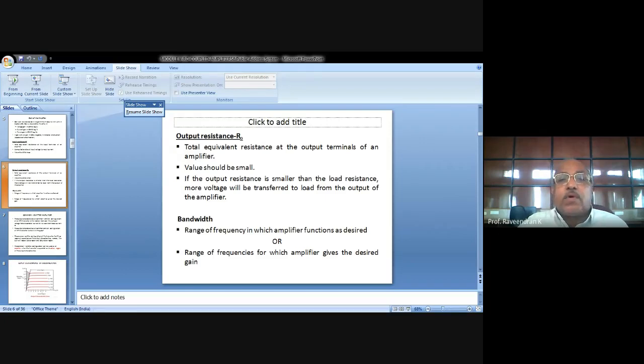So what are all the important parts here? The transistor in common emitter configuration. Resistors R1 and R2 give the potential divider or voltage divider bias network. It provides the necessary DC voltage VCC to keep the transistor in the active region of operation, that is, the base emitter junction in forward bias and the collector base junction in reverse bias. And RE, here RE I have just shown you. This emitter resistance RE is nothing but the same RE you have seen here.